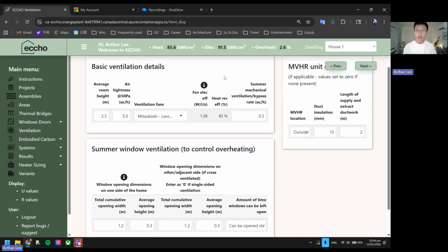So now if we look at the result quickly, we managed to bring the heating demand down from around 130 to 85 by literally changing three things. I have to be honest. We use 140 framing. We introduce heat recovery ventilation. And the third thing is free, because we only just specify a different low-E glazing that doesn't cost any money. So I'll say those few actions are probably quite effective and will most likely give us a good return on investment.